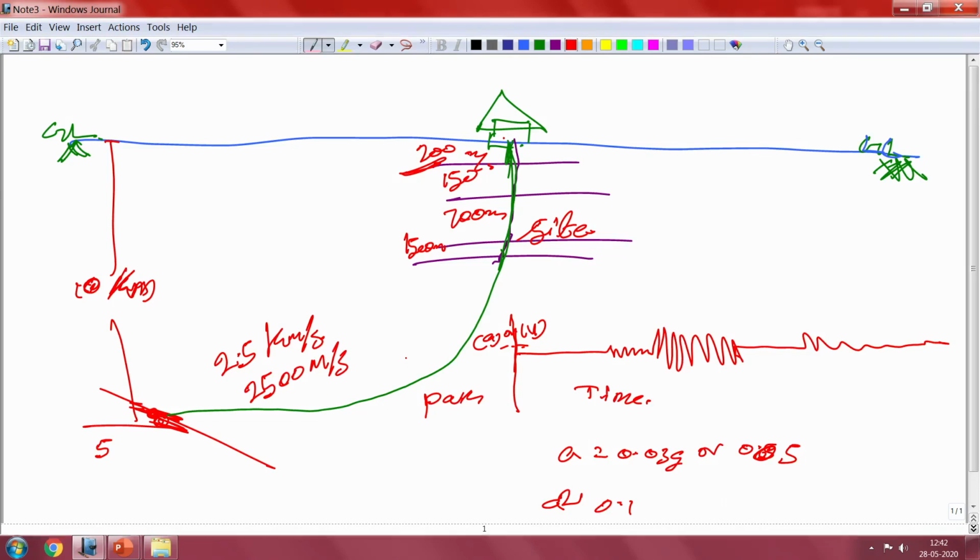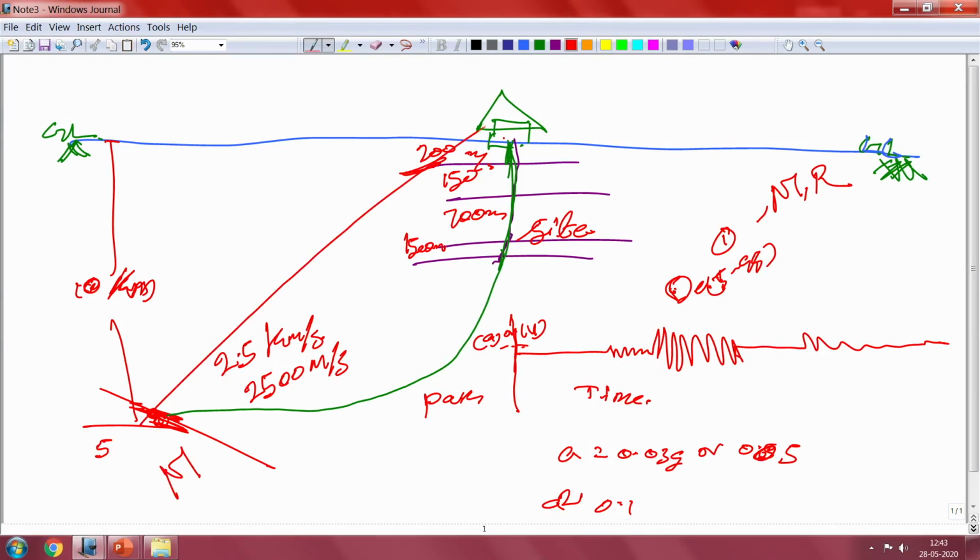Generally the durations will change because of the several layering systems. The source duration and the path duration will change due to the site condition. So, the duration factors are very important, and very specific to a particular location. As you have seen, for each earthquake you can estimate the significant duration for 5 to 95%. I am giving the example, and one value for a given M and R. M is the earthquake magnitude, R is basically your distance.